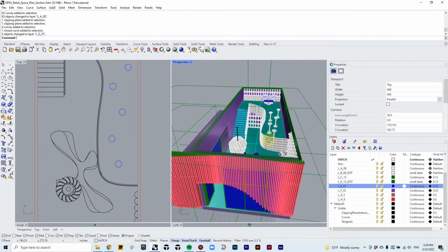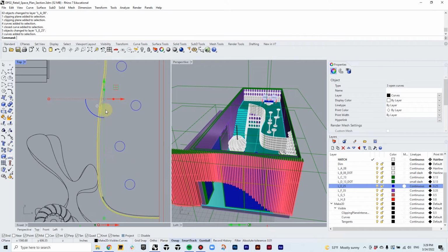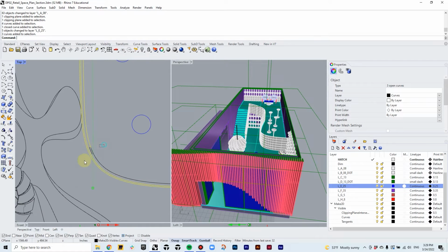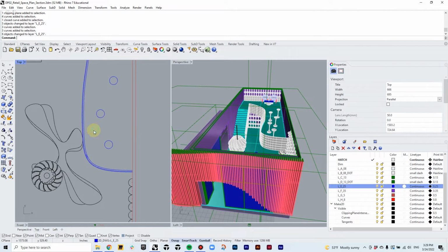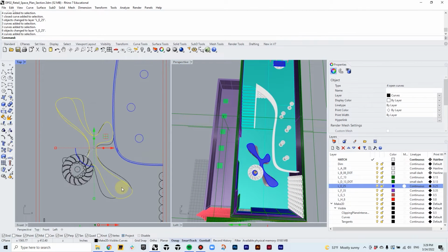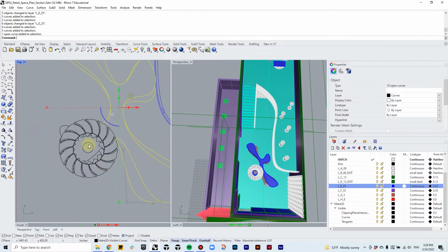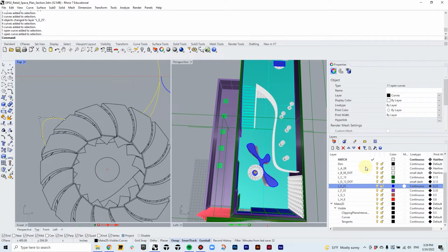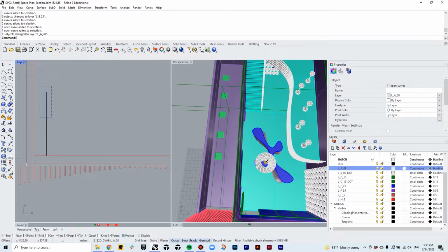And then all of these lines here for the second floor kind of handrail, they can be 0.5, 0.25. The lines on the table on the bottom level, they are very far away from the view. So I'm just gonna give them 0.08 hairline. The door on the bottom level should be hairline 2.